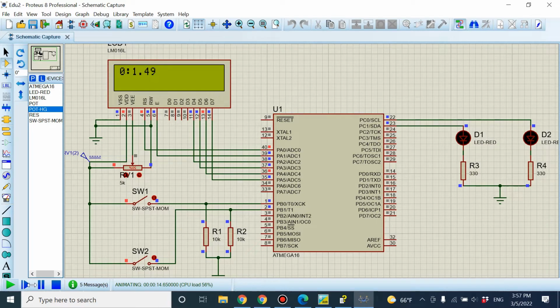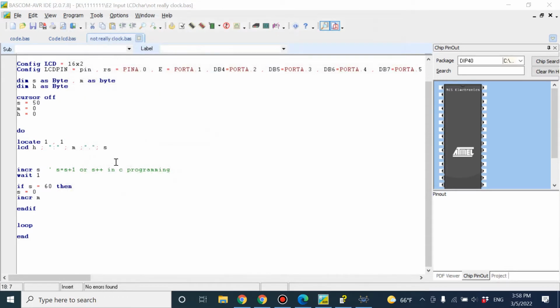Okay, right now as you can see there is a 9. It's not 9 here, it's not 79. It's just a 9 from the old value, but it didn't go away from the LCD. So I just say CLS each time you're going to show something. So that problem should be gone.